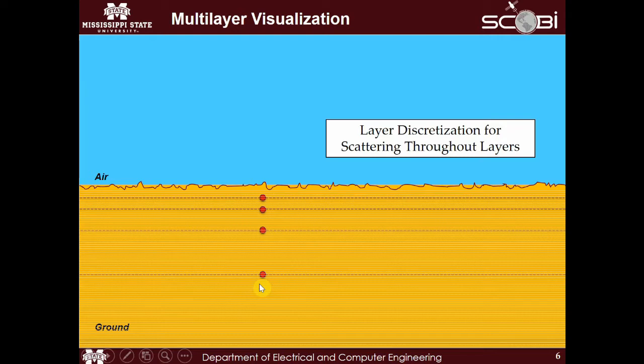And within our input file, what we've decided to do is label things as being discretized with a variable called del z. And what that does is it breaks the soil moisture profile up into components as big as the value that you input. So in that file, you'll see that it is 0.001 or 1 millimeter for intents and purposes of this problem.